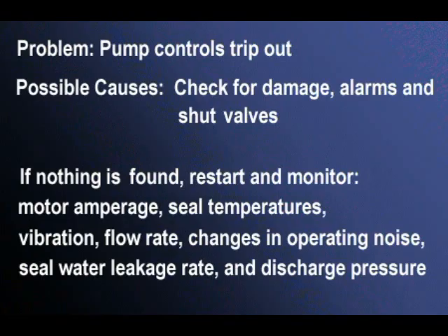Problem: pump kicks out. Check for visual damages and alarms or shut valves. If cause of failure can't be found, start motor and monitor amperage, temperature at seals, vibration, flow, noise, seal water, and discharge pressure.